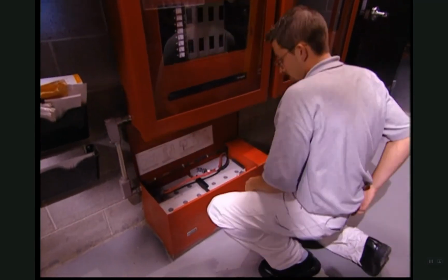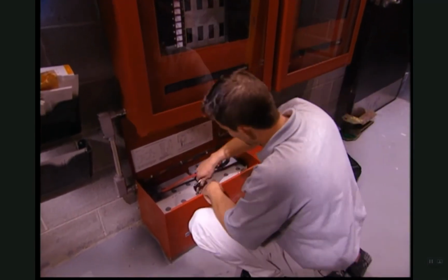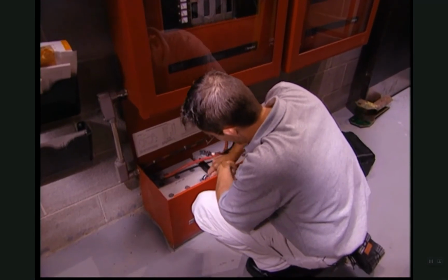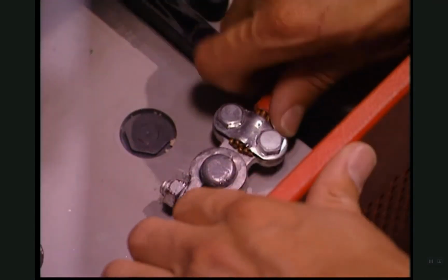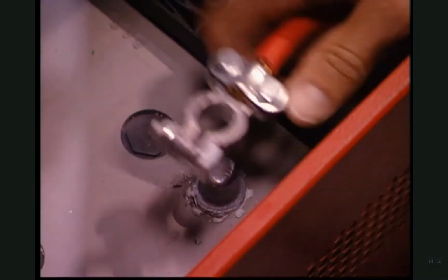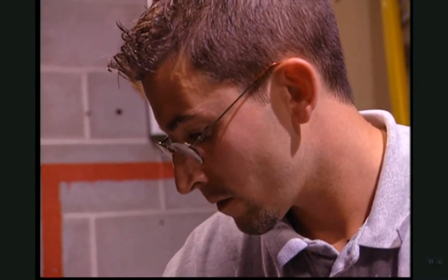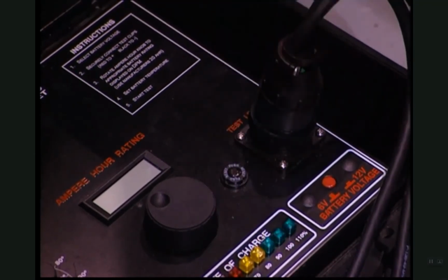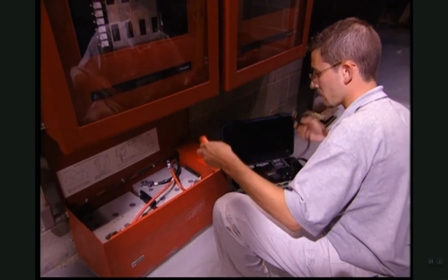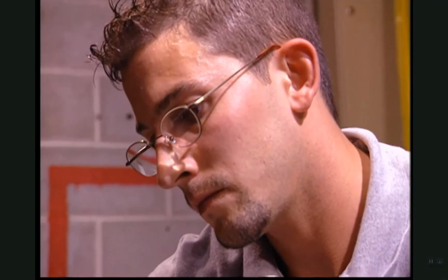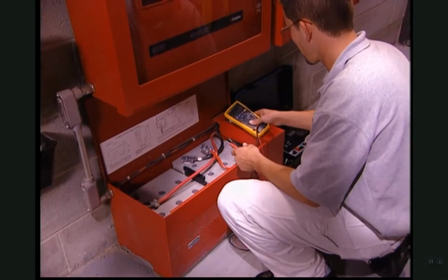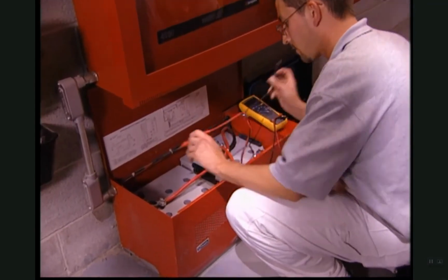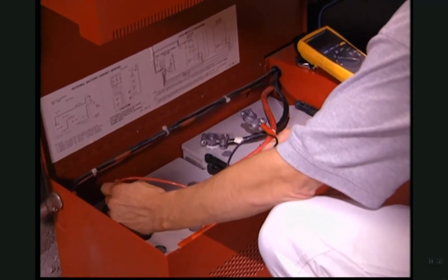How often you inspect and test backup power supplies will depend on the type of battery. Nickel cadmium and sealed lead acid batteries need to be inspected semi-annually. Non-sealed lead acid batteries should be inspected monthly. The schedule for battery testing varies with the type of battery. More frequent battery testing may be required at a supervising station.